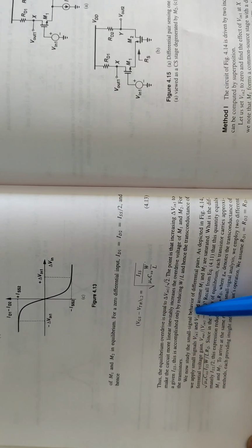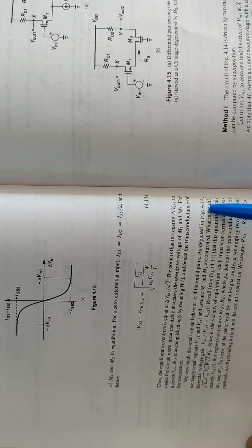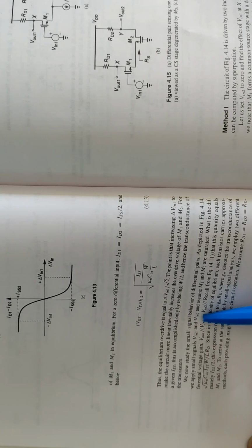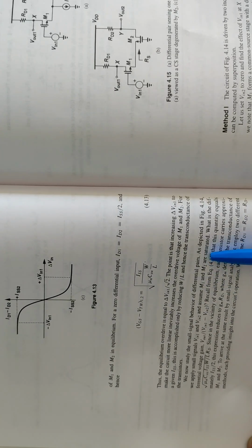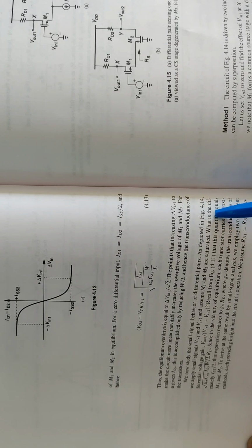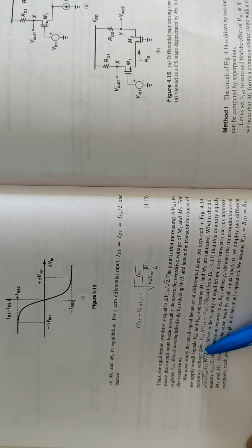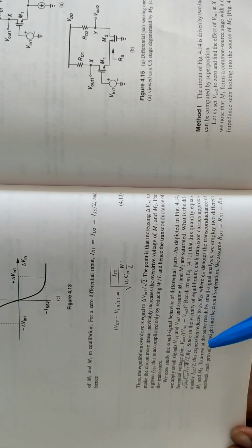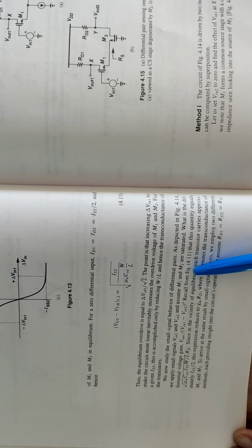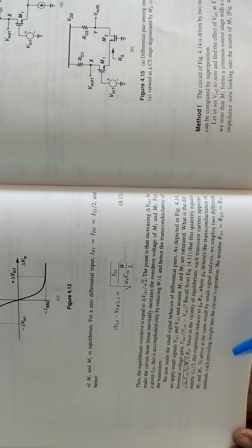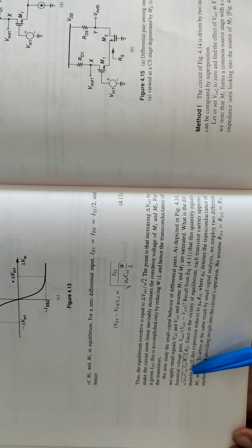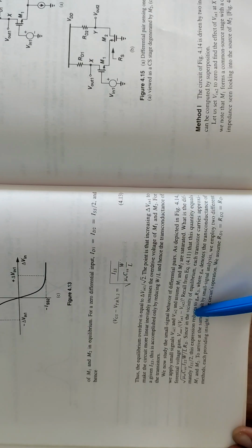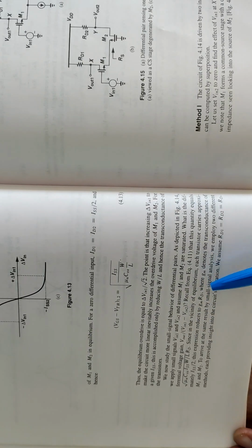Now we study the small signal behavior of differential pairs as depicted in the figure. We apply small signals Vin1 and Vin2 and assume M1 and M2 are saturated. That is, what is the differential voltage gain, Vout/(Vin1 − Vin2)? Recall from the equation that this quantity equals √(μn Cox ISS W/L) RD, since in the vicinity of equilibrium,